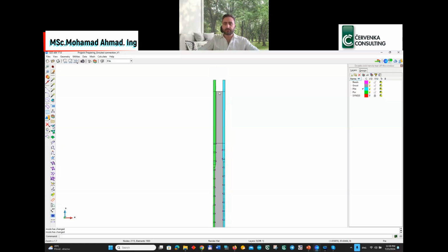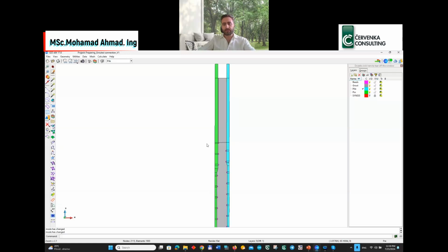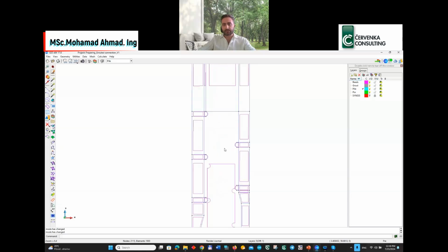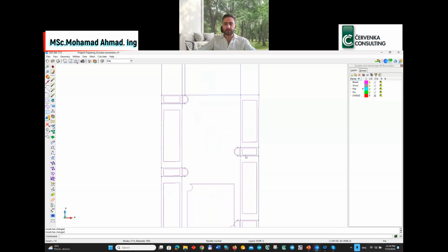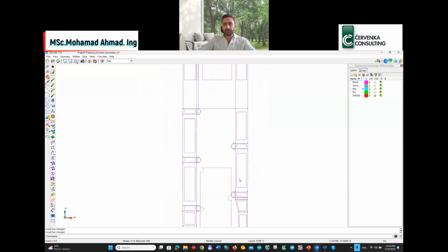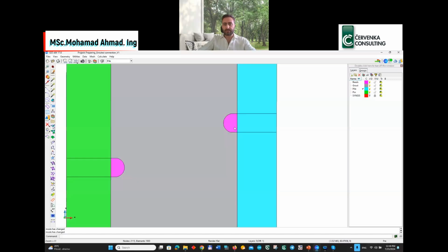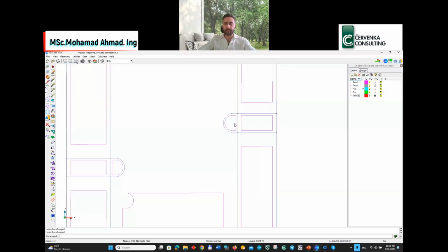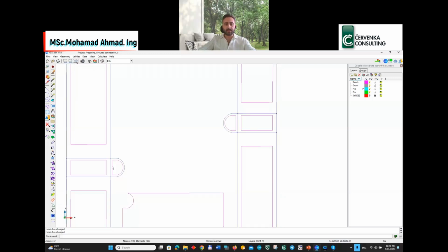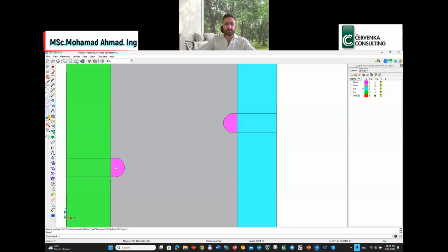So as you can see here, we have just a 2D model. It's just surfaces. And as I mentioned, like the divisions, just to have compatible mesh, as you see here, this surface for the beads is sharing the same line with the surface here for the pile. Again, here the same, the surface from the pin sharing the same line.